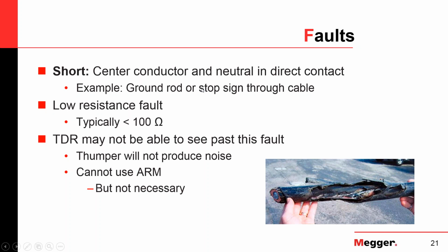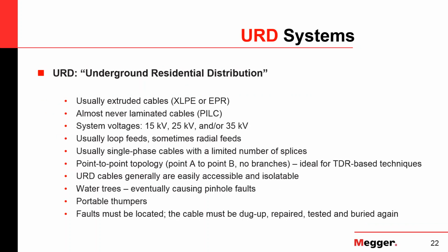The problem also with those faults, I just want to mention it, since it's a short, you will later see that there's no possibility to create a flash over there, a spark. And so you also cannot really use the arc reflection method on those faults.